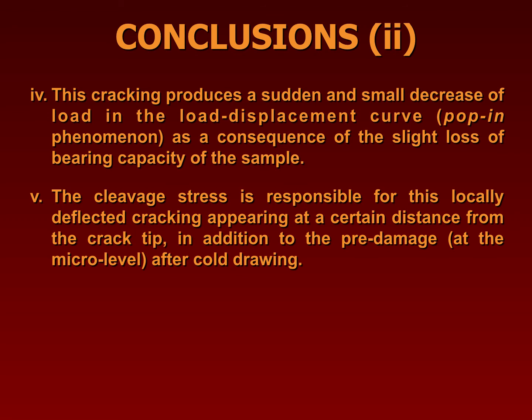The cleavage stress, sigma XX, is responsible for this locally deflected cracking, axial microcracking, appearing at a certain distance from the crack tip or from the blunted crack tip, in addition to the pre-damage at the micro level after cold drawing.